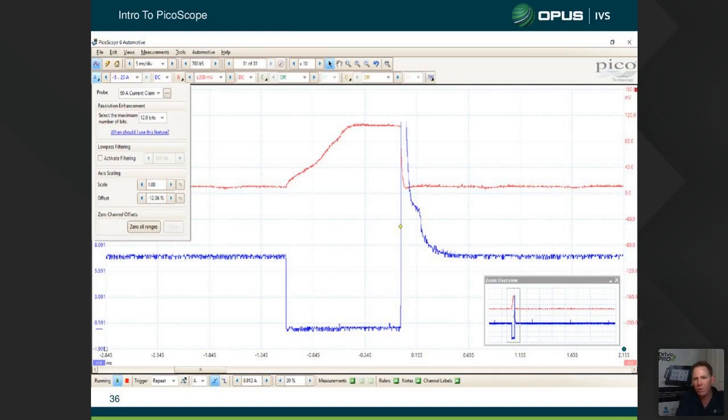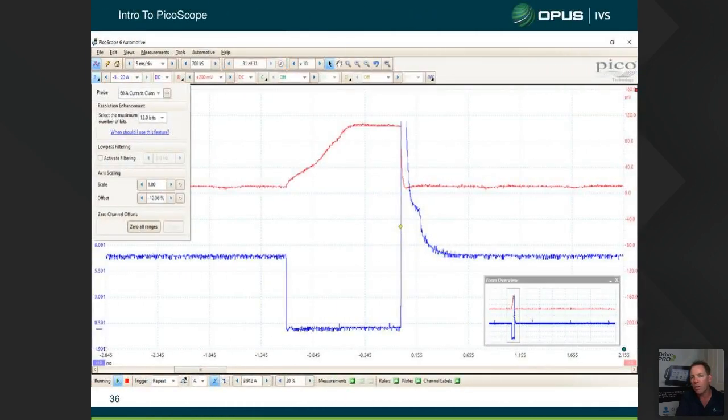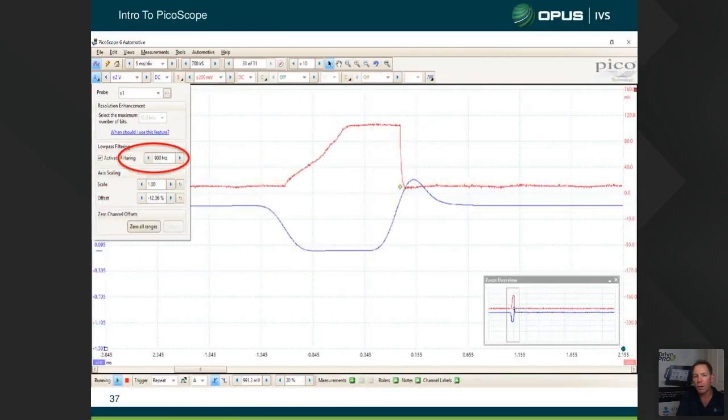So here's our current flow through our injector. Here's our voltage in the injector. There's no filter added at the moment. If we go to our next screen, where we've actually turned the filter on and then increased that frequency up as high as we can go, you can see the voltage change ridiculously because we're on channel 8. Now, you can see we've lost a lot of our signal. We've actually filtered that signal out. Any frequency that goes above this range, we've filtered out by changing our frequency value inside there.